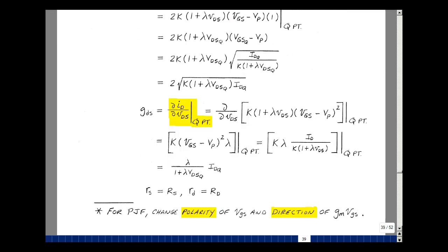In this chapter on page 19, we found R0 as the change in the collector emitter voltage over the change in the collector current. Here, same idea, we're just going to take the reciprocal of that. If we were finding the reciprocal of R out, that would be the change in I sub C over the change in VCE. And the corresponding things now are the change in the drain current and the change in the drain source voltage, evaluating that at the Q point. Take our expression for the current saturation current, and now take the derivative with respect to VDS. That's only in this term right here, so this is a constant, and then the derivative of this with respect to VDS is 0, and then just 1 times lambda.